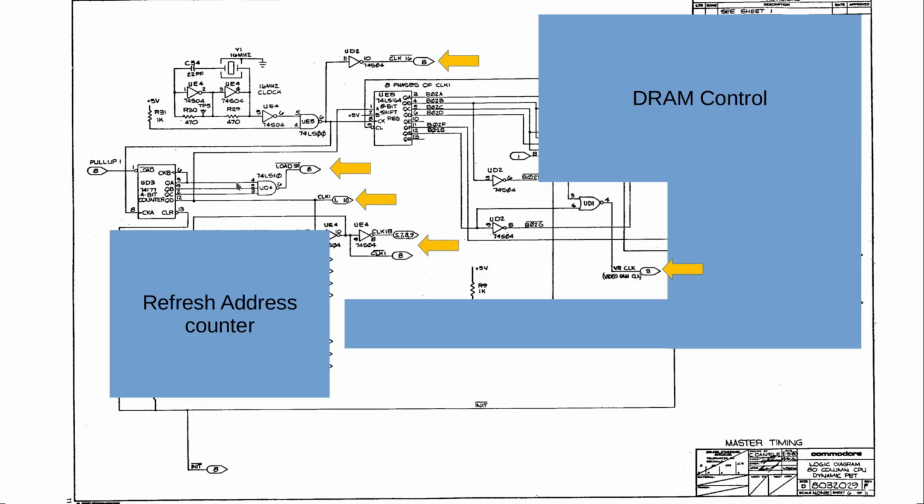Here we have the shift register load, and remember this is the 80 column machine, so the pixel clock is 16 megahertz. You can see that up here, and here we have 8, 4 and 2 megahertz clocks, and they are all NANDed to create that shift register load signal, which means that this is at the end of every half cycle for the system clock. We'll see that as I've shown it. Basically every time the system clock changes, we load the shift register, as we've seen in the timing diagram before.